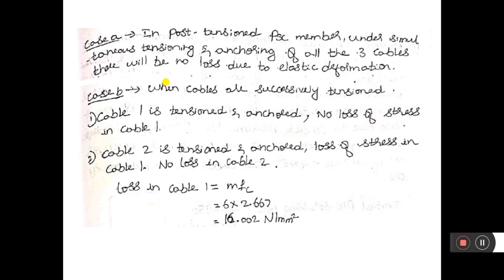So in a post-tensioned PSC member, under simultaneous tensioning and anchoring of all the three cables, there will be no loss due to elastic deformation. Therefore, loss of prestress due to elastic deformation is equal to 0 for the first case. Now coming to the second case.